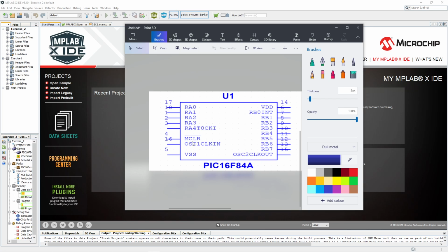You care more about the oscillator OSC1, to which you put the frequency that you used in the simulation. For example, if in the simulation with MPLAB I use a frequency of 1000 Hz, then I'll connect 1000 Hz through this clock here. Master clear: when zero is input through it, it just sets everything to zero. It makes everything blank and starts all over again.